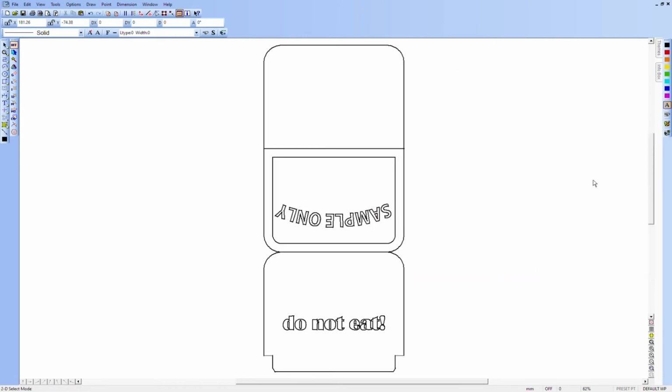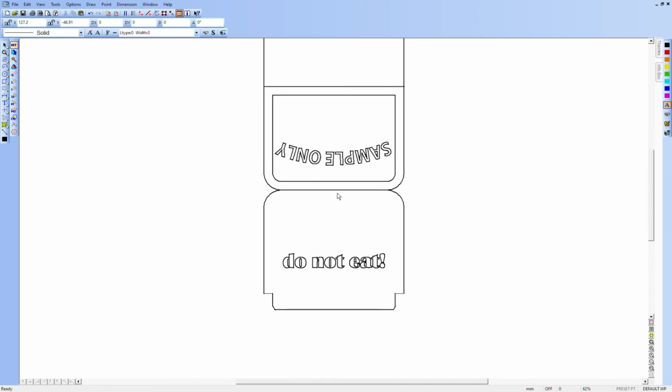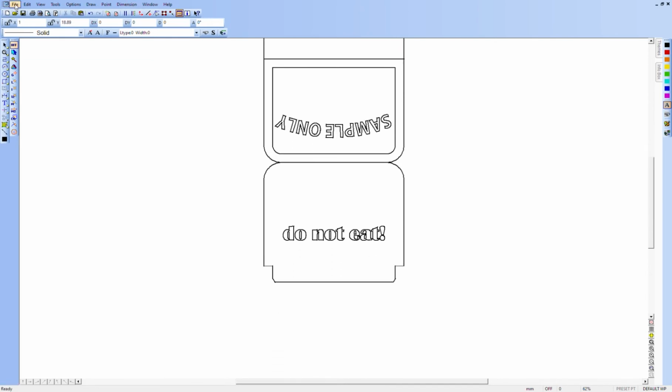Ctrl W will fit everything to the window and refresh the view. We now have some of these parts nicely stacked, saving cutting time and eliminating any wasted wood between the parts. All that's left to add to our batch cut file is the parts for the base. It will be made of 2 layers of the same part.